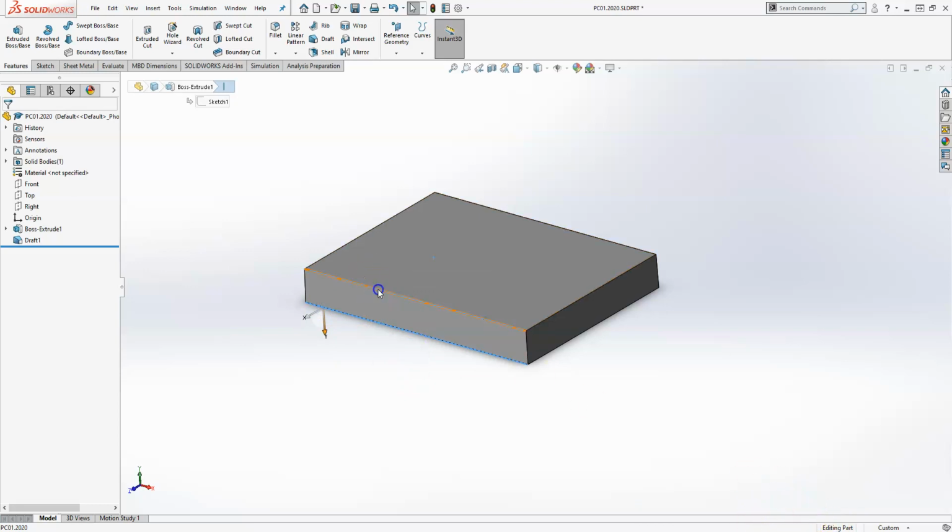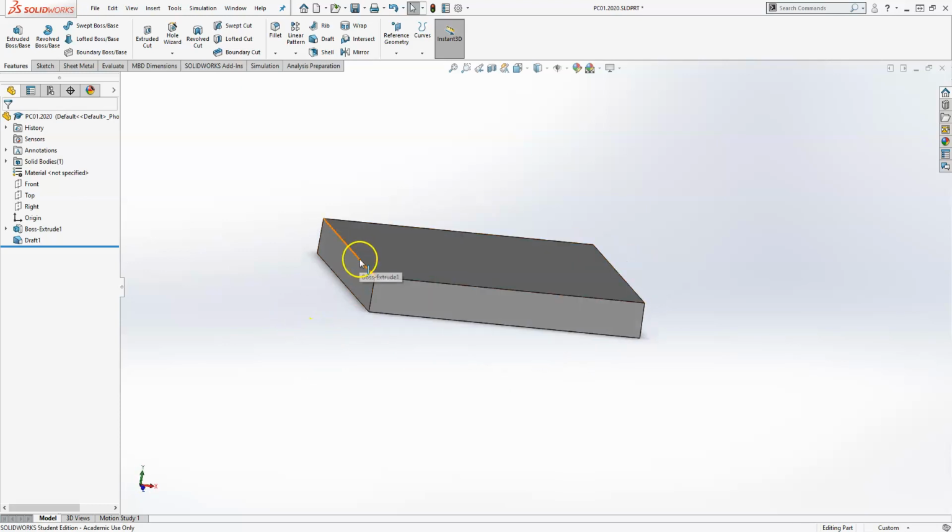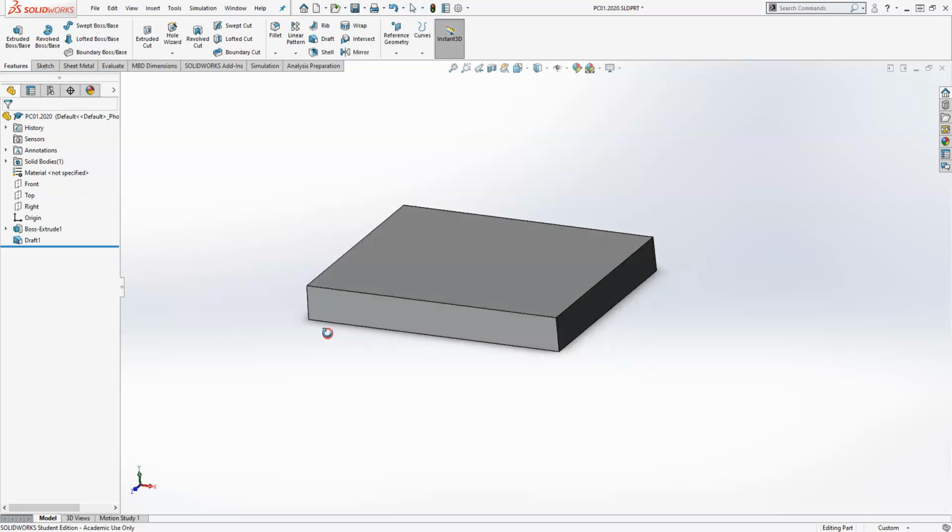And then if we select that other line, you'll notice that it's not as long as the bottom line. And that's because this is drafting up to a point at a 1 degree. So all four of those sides are drafted in. You'll see that without having 60 or 80 as your dimensions.